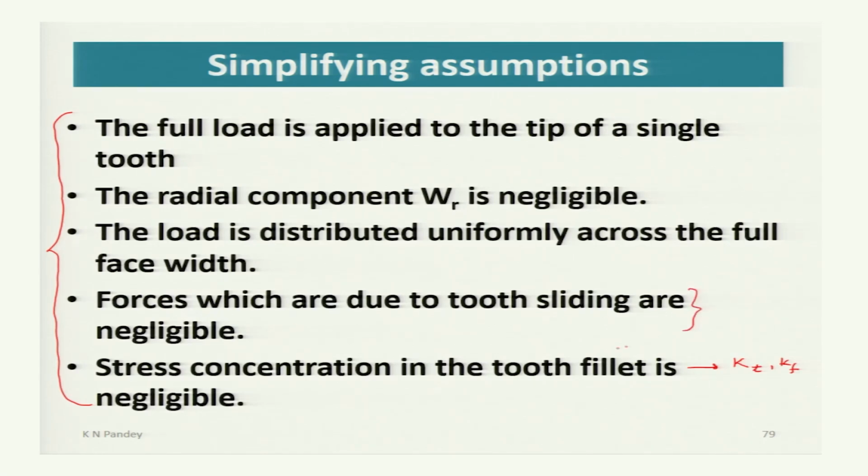Forces due to sliding are negligible. This analysis was done for the cases where the sliding was negligible, only rolling action was taken. The load was assumed as uniformly distributed along the width. The radial component Wr is negligible because Wr will apply compressive load, and the compressive load is not detrimental for fatigue, and the full load was applied at the tip of a single tooth.